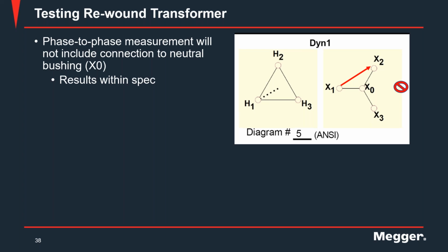That's a test done using AC quantities, where generally the industry standard is about 10 kV. You apply 10 kV to the winding, and then you record the current that is demanded by the winding as part of that process. That current that the winding demands is used to establish the baseline working flux in the transformer core. Excitation current measurements reflect that activity,